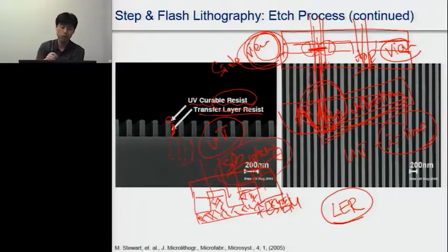But those diffractions do not actually affect the pattern dimension changes or line edge roughness, because all those patterns are physically transferred by the master mold.